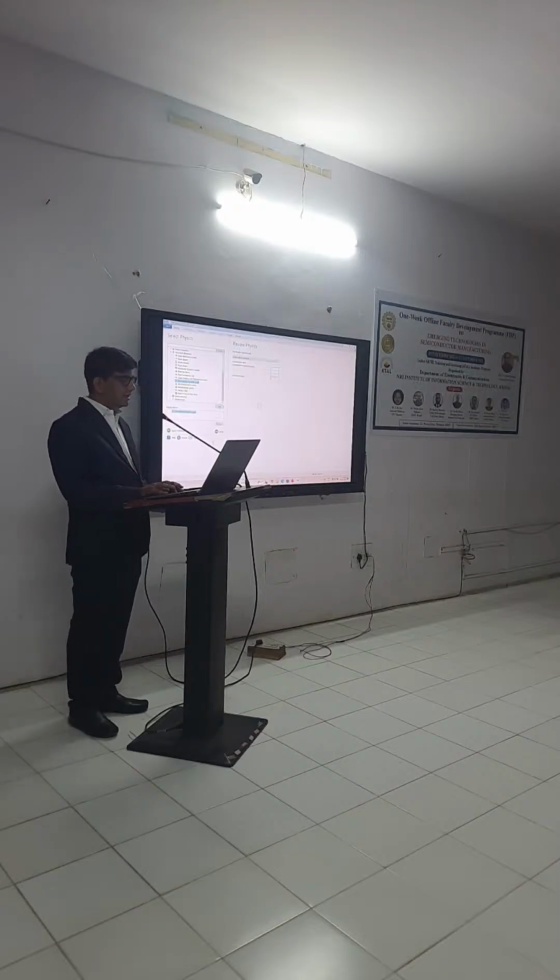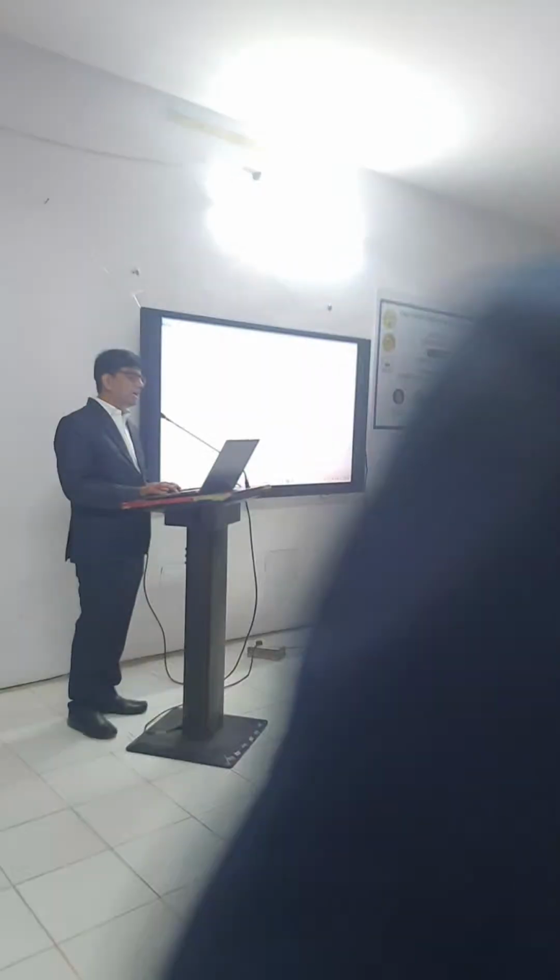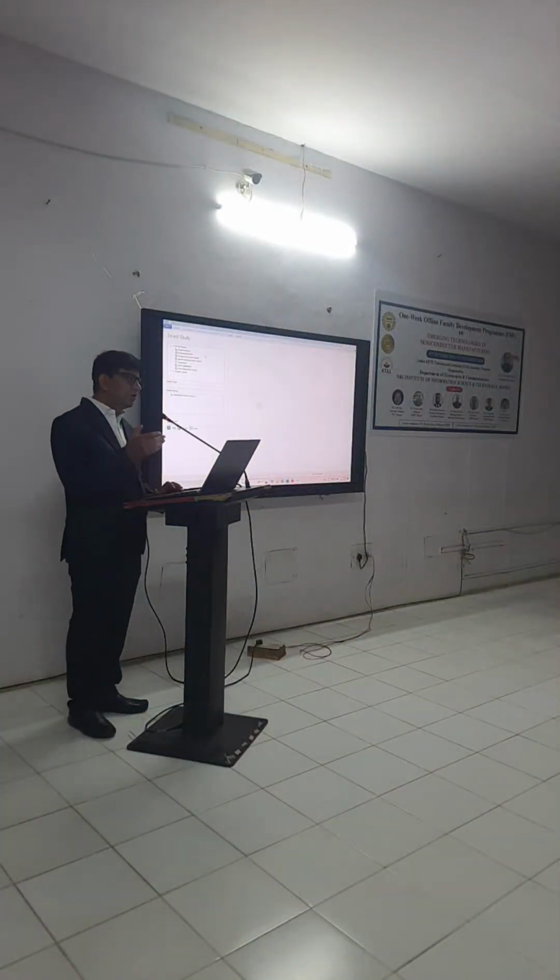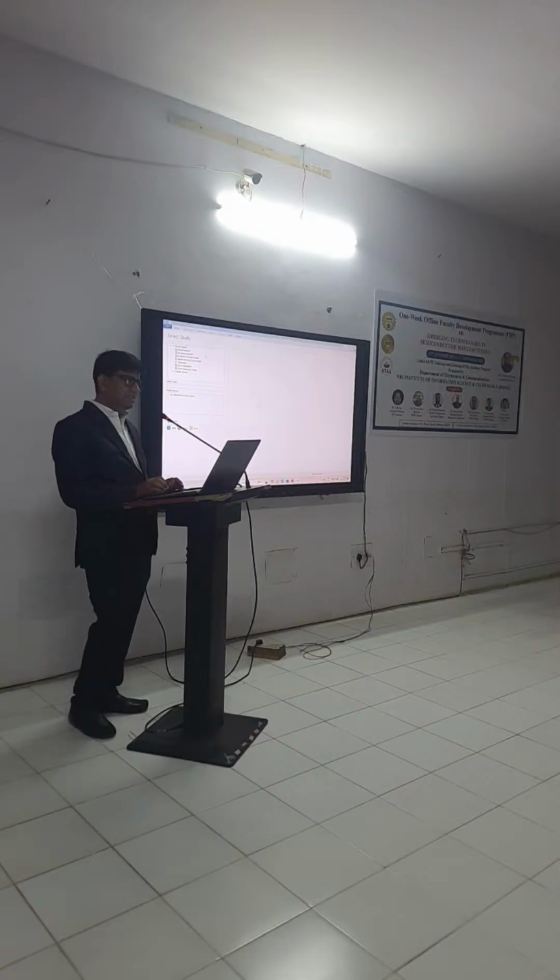Okay. Then I will go to study. So what kind of study do I want to perform? Here we have different types of study: eigenfrequency analysis, frequency domain analysis, frequency domain modal analysis. As per your requirement, generally we use this eigenfrequency analysis to find out the different eigenmodes of your device. So you can easily find out what will be the device frequency.